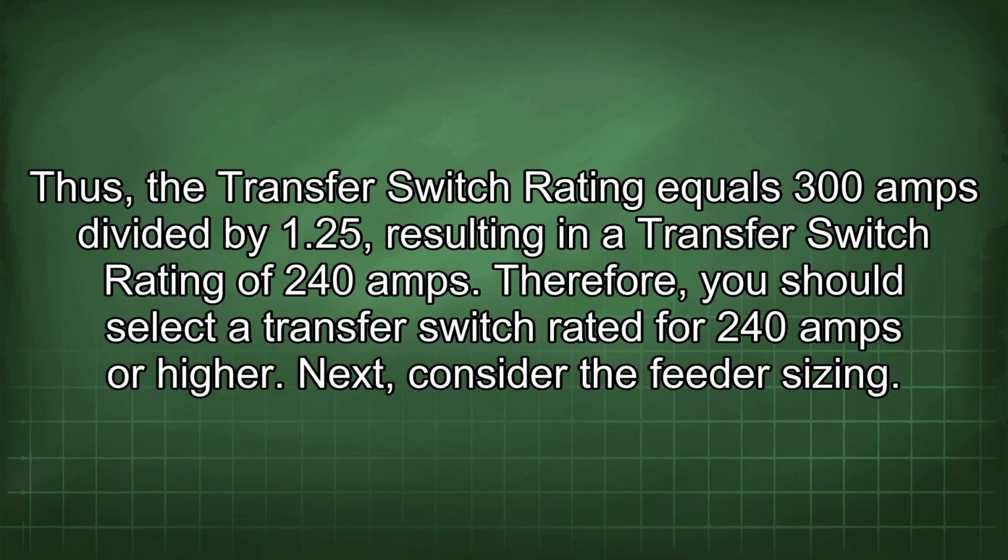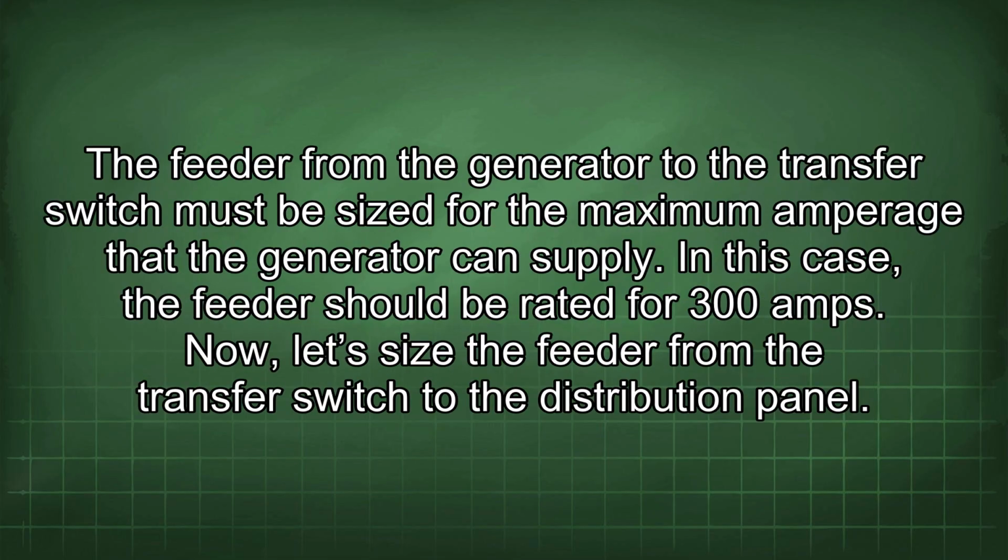Next, consider the feeder sizing. The feeder from the generator to the transfer switch must be sized for the maximum amperage that the generator can supply. In this case, the feeder should be rated for 300 amps.